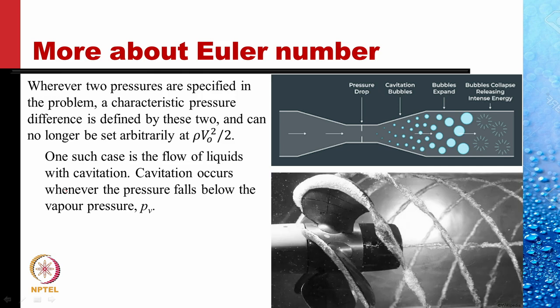This picture shows the vapor trail in a propeller of a ship. These are water vapor trails that you see. The pressure at the tip of the blades is very low, below the cavitation pressure, and the vapor bubbles form a nice, beautiful picture as seen here.